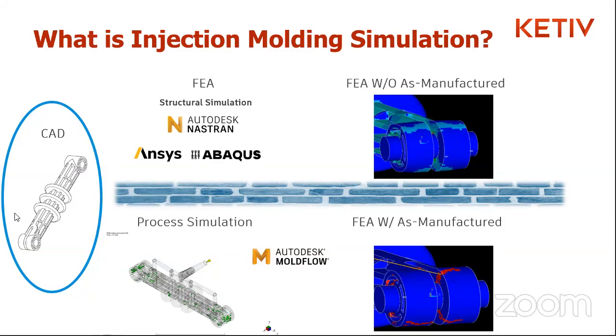Yep, just got to look close enough. Yeah, some of these artifacts like weld lines have a strong signal to where you might run an FEA with a perfect CAD model and it looks great, where it's actually, in this case, an example where it fails differently along the weld line. In other areas, things like residual stress or orientation effects, especially with composites like fiber filled material.